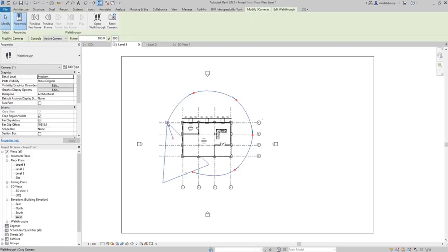And then for the other main frames, I'll need to do the same thing. So I'll get back here, and then you'll notice that the view is not showing the building. So just grab the magenta dot and make it a little bit rotated towards the building.